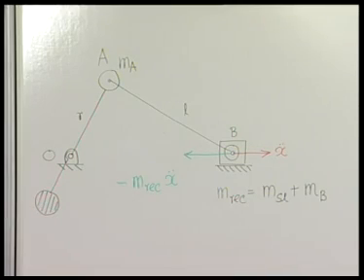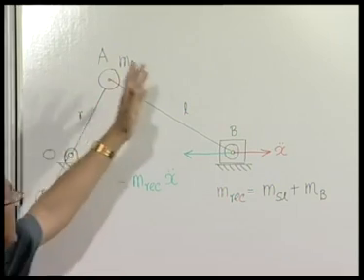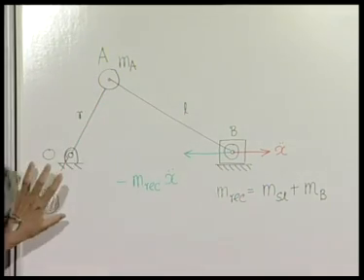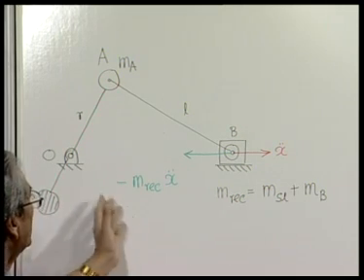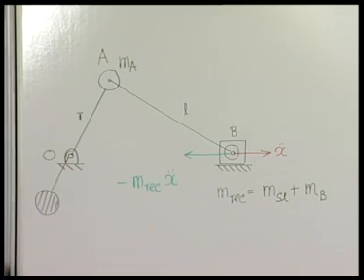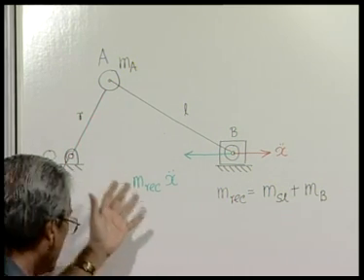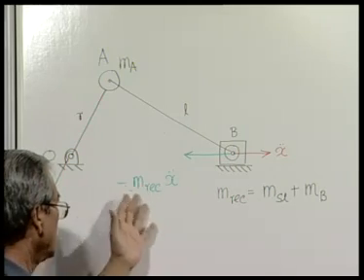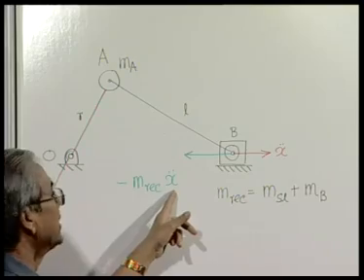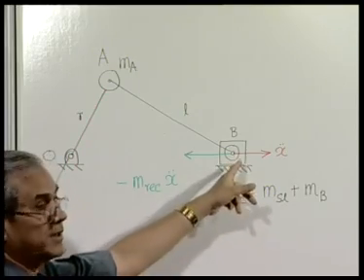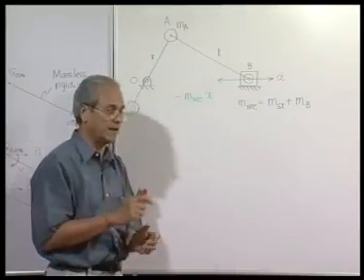So, therefore, when the rotating part is taken care of by a counterbalance, the only unbalanced force in this system is the reciprocating inertia force. Next we have to find out the magnitude etc. of this reciprocating unbalanced inertia force, and to do that we have to have the expression for the acceleration of the slider, and next we will do that.